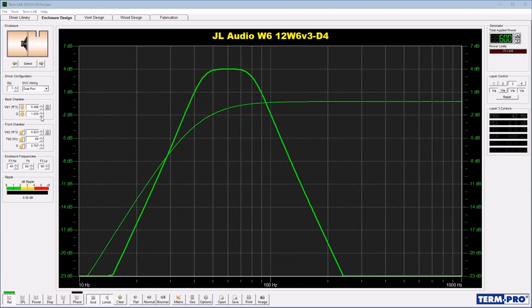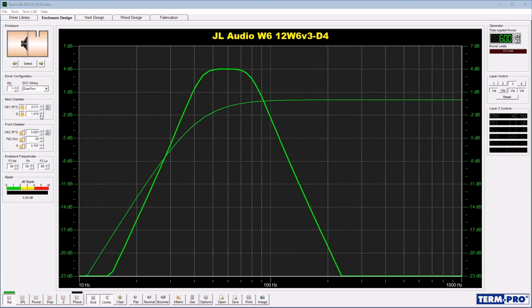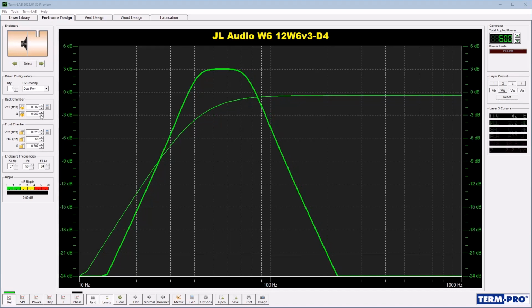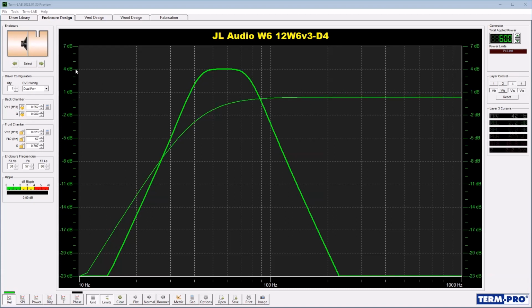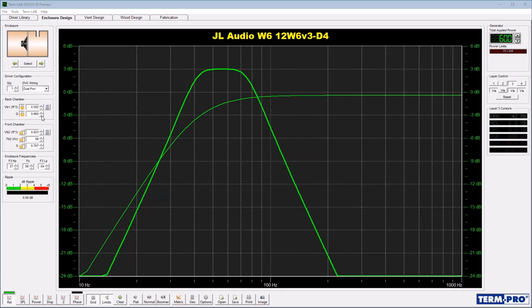Or maybe we even want to play it a little bit lower. Let's dial this down. Let's say we change it to 55 hertz. A ton of energy in this range, in this area right here. So you're getting a lot more sound without any additional power. Now look at the trade-off. You see now I'm only up 3 dB. So as I change things, I can see over here now it's changed to 4 dB. So there's these trade-offs as you adjust. There's gain bandwidth trade-offs here.